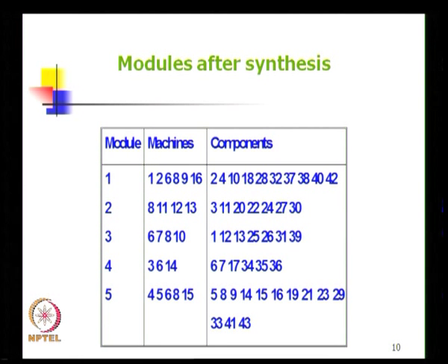Suppose we get a number like 1.3 machines of machine number 2 required. Then we realize that it is not enough to have one machine of machine number 2, but we need to have 2 machines of machine number 2. Therefore, when we actually implement it, these 6 machines in the cell may even result in 8 machines, with more than one required at some point. So, this aspect is called capacity planning. Capacity planning has to be done.